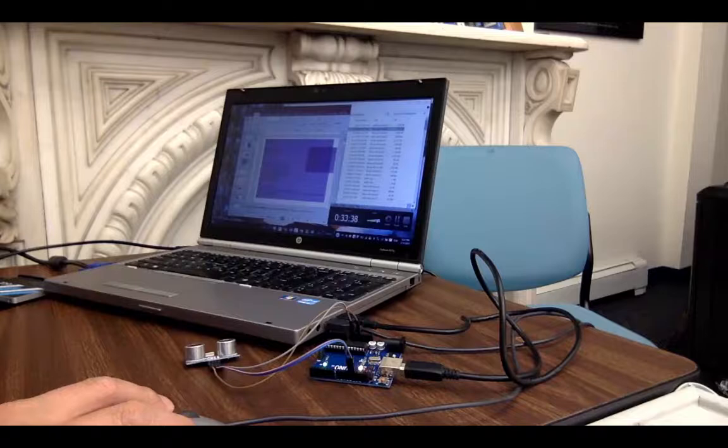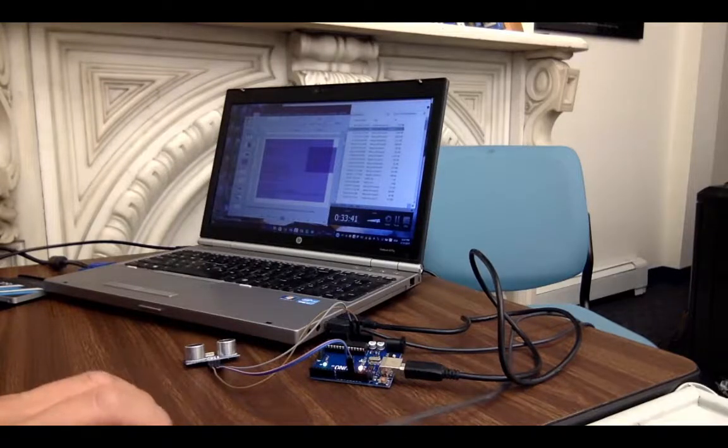So click this, compile, and watch here to see if any errors. If you have any errors, then you have red colored text. If not, then white. Compiling sketch is currently going on, right? Okay, so compile is done.